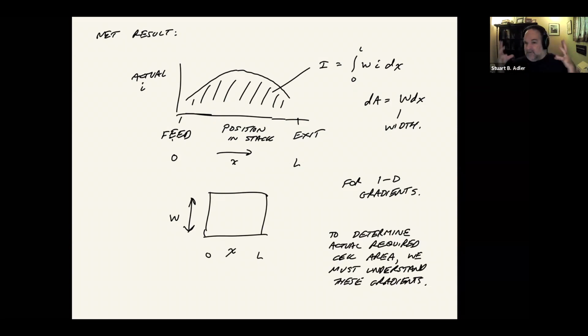On the other hand, if you make everything out of metal interconnects, which tends to be the modern way of doing things, as temperatures have come down for solid oxide fuel cells, people have been able to use metals, stainless steel or variants of stainless steel to basically act as the interconnect materials. In those types of systems, the thermal conductivity of the steel, the metal itself, is fairly high. And that's good because it actually helps distribute the heat. In fact, you could argue that the main role of a metal interconnect, its benefit, is the thermal conductivity because it allows you to spread the thermal energy everywhere really easily.